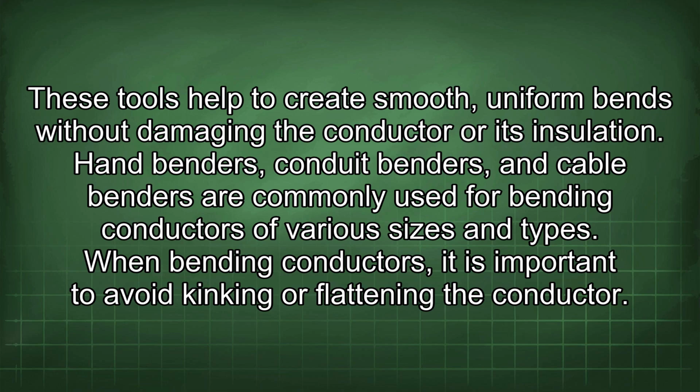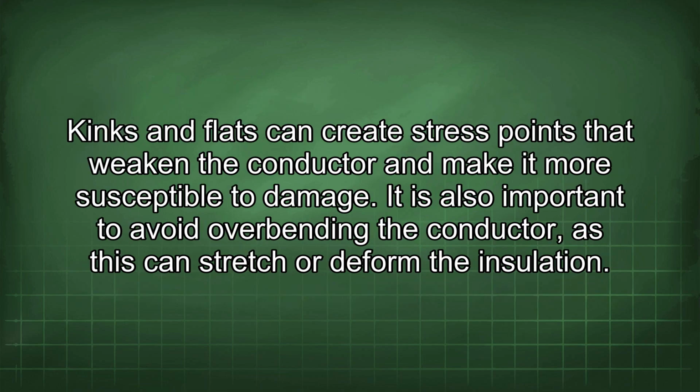Hand benders, conduit benders, and cable benders are commonly used for bending conductors of various sizes and types. When bending conductors, it is important to avoid kinking or flattening the conductor. Kinks and flats can create stress points that weaken the conductor and make it more susceptible to damage. It is also important to avoid overbending the conductor, as this can stretch or deform the insulation.